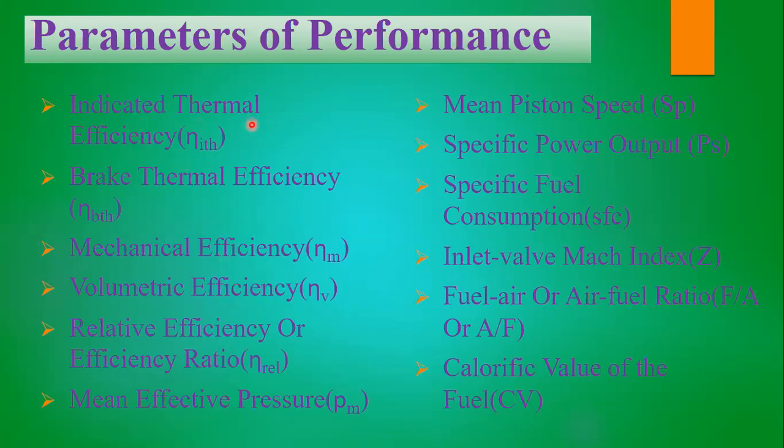Indicated thermal efficiency is a very important factor, because if the indicated thermal efficiency is high, then the brake thermal efficiency is high. Why? Because whatever energy is developed also depends upon the number of losses. Of course the indicated thermal efficiency is high, but if we minimize the losses, then most of the energy is going to convert into brake power or